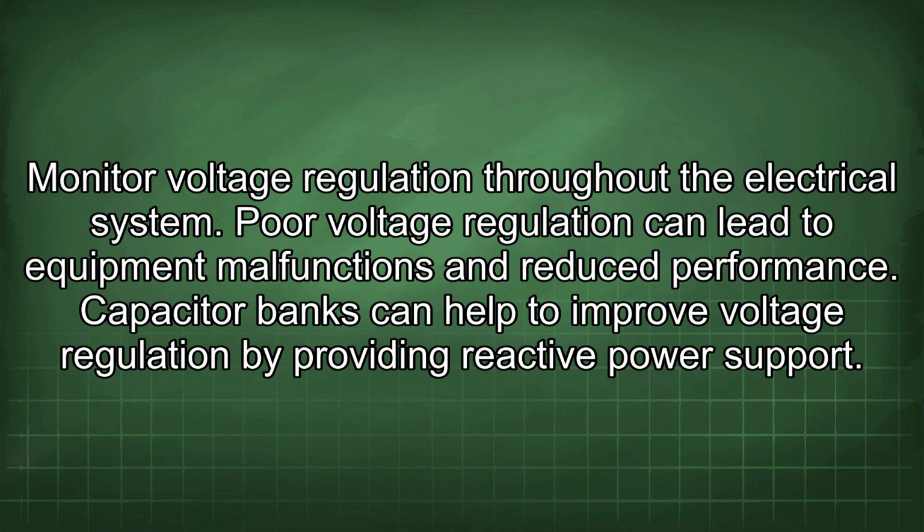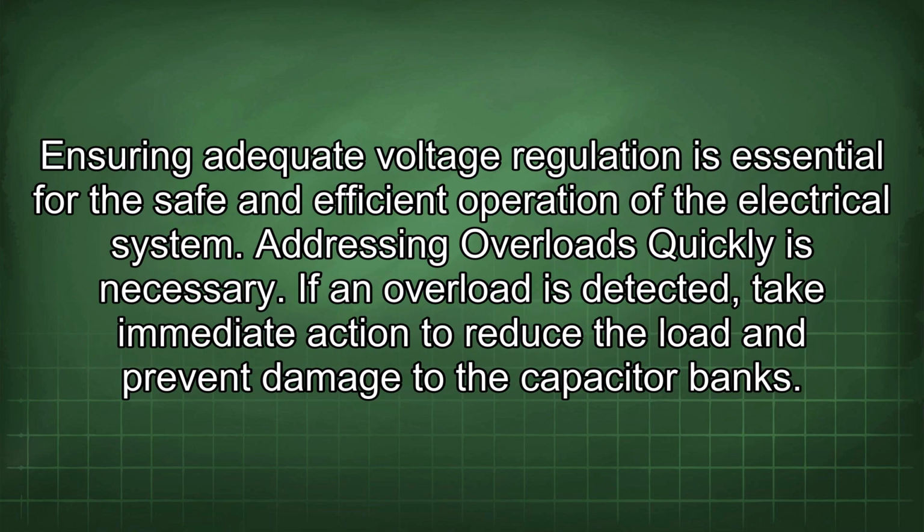Monitor voltage regulation throughout the electrical system. Poor voltage regulation can lead to equipment malfunctions and reduced performance. Capacitor banks can help to improve voltage regulation by providing reactive power support. Ensuring adequate voltage regulation is essential for the safe and efficient operation of the electrical system.